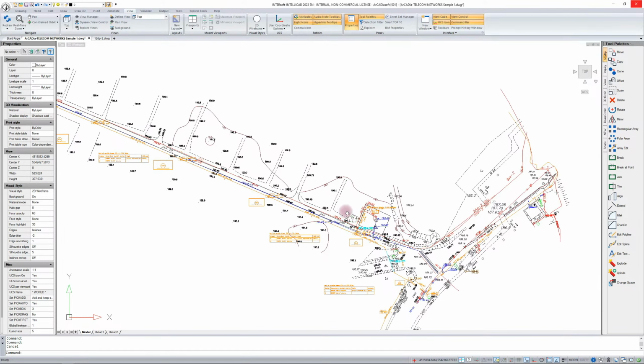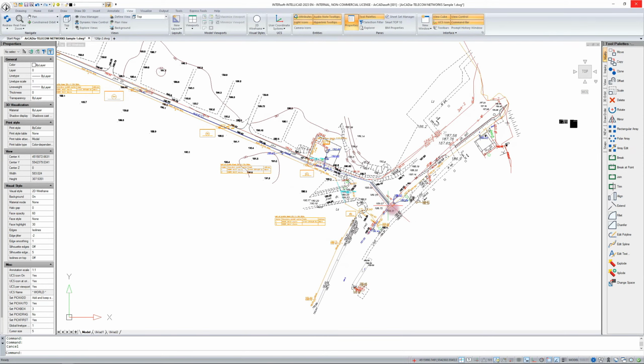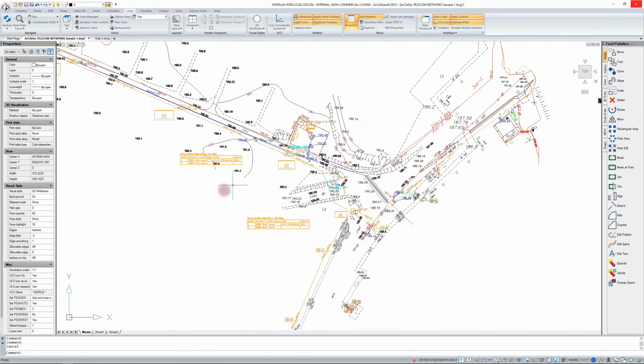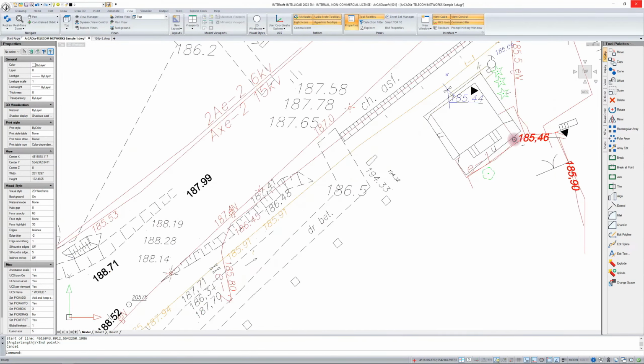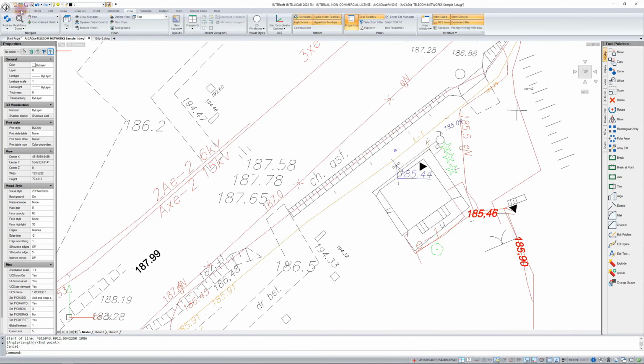Now I would still like to discuss the coordinate system settings. We have a global coordinate system, which I think we talked about in the 2nd presentation when we discussed drawing, but as with this drawing, it would be useful that when I draw some elements, I would like them to be in relation to, for example, a street or some element on the document. And now, when I draw with the ortho option turned on, the lines will be horizontal or vertical relative to the screen. It will be the same on the left side. And here I would like them to be angled a little bit. It will be easier for me if I switch the global coordinate system to the local coordinate system.